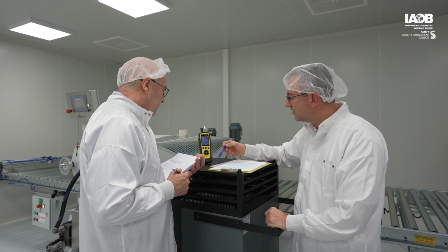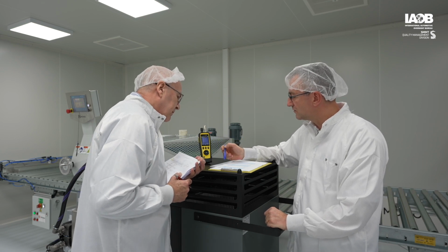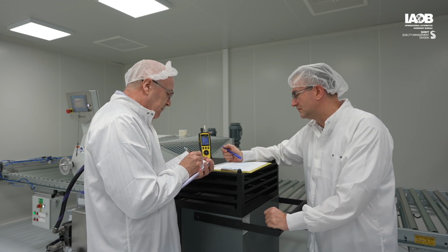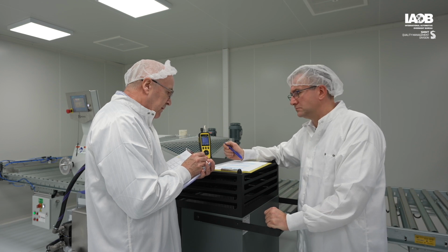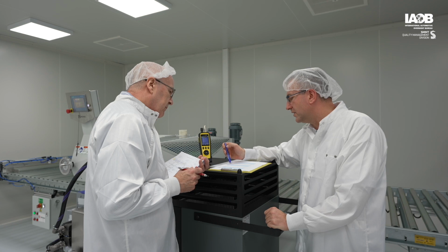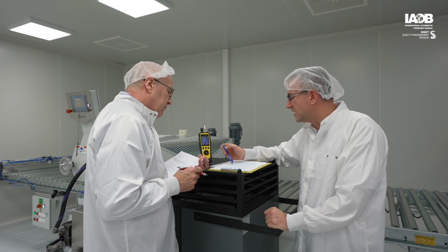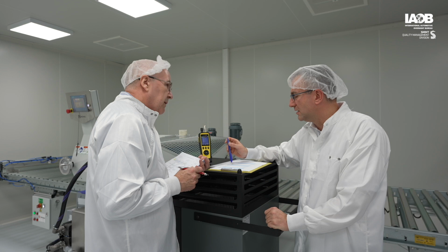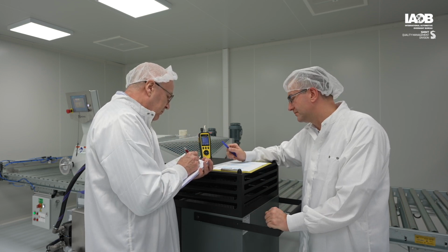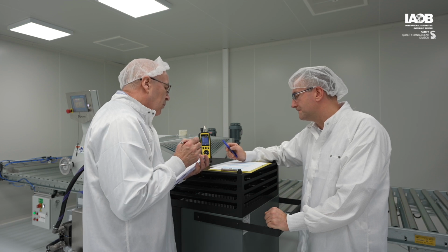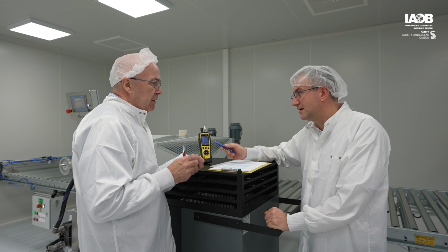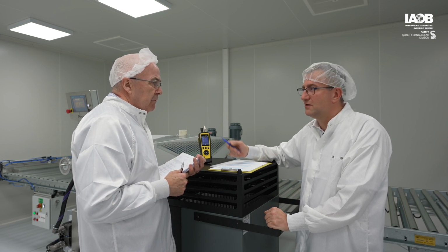And what we measure here, we also make a statistic. We measure 4 times a day. And if we see that we are out of the range, if we have more than 5 particles bigger than 10 micron, we stop the production. Okay, and what could be the cause of that, that we've got the high particle count? Incoming people and incoming materials.